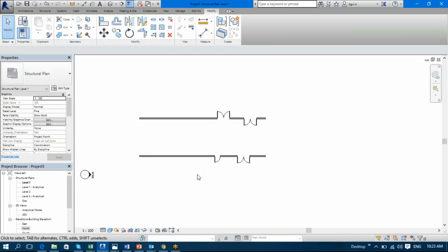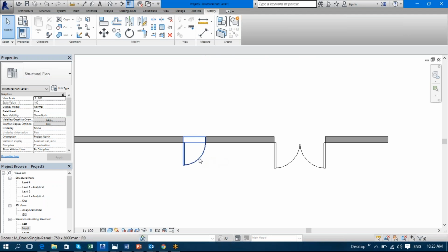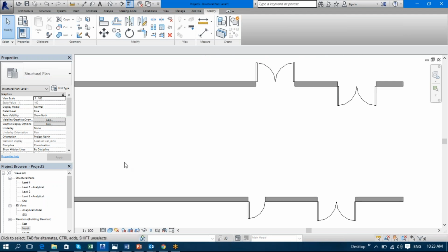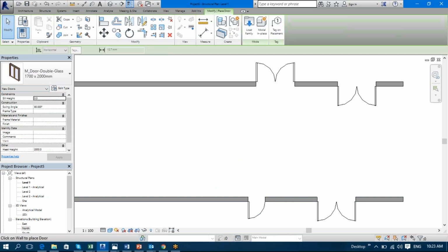But yes, you can copy it. But then there is another different shortcut called create similar. You don't need to again select the family and then go to type selector, change the type and then create it. If you see that you have already created it in the family, in a plan, and you're working very closely in this, you don't need to disturb yourself.